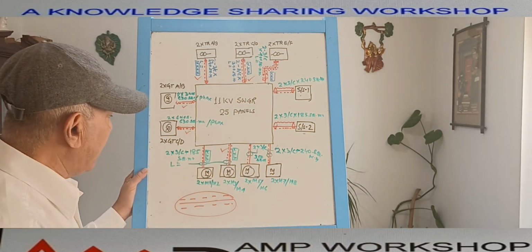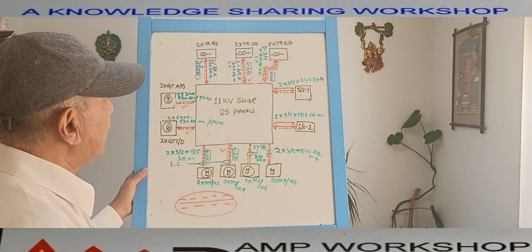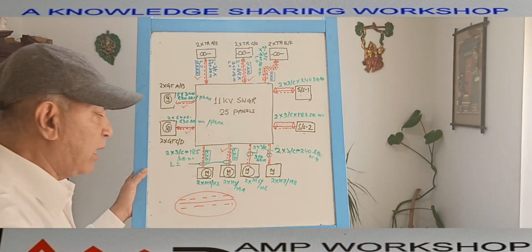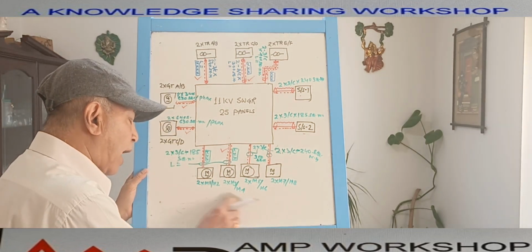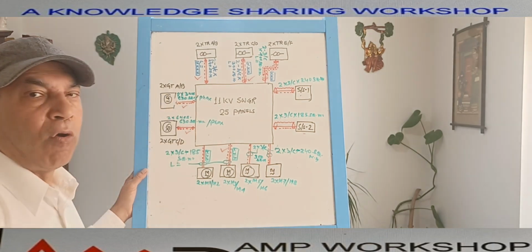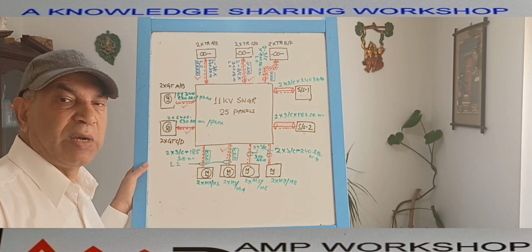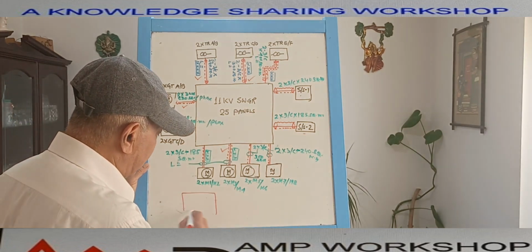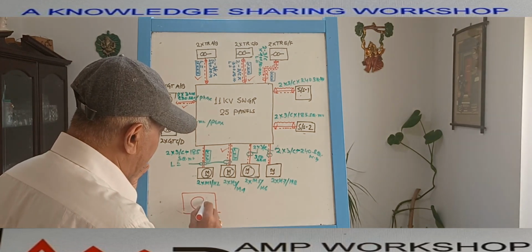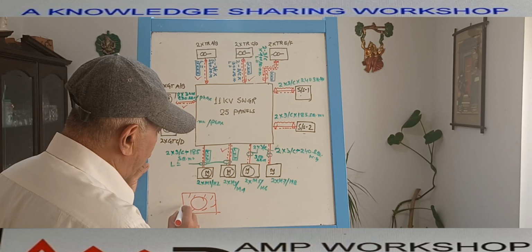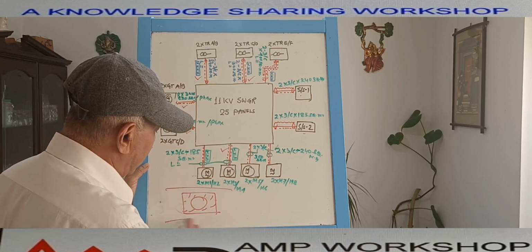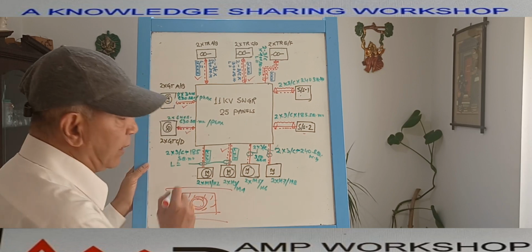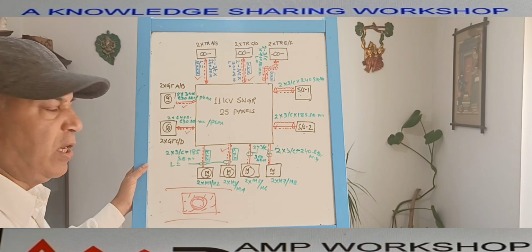Then there is another symbol we use, for a cable buried under the ground but not directly buried. This cable is laid in a concrete trench or a duct bank. We make a concrete duct, and inside there is a pipe. These are the concrete blocks under the ground, and through this duct, through this pipe, the cable is passing. This is mainly used in the oil field.